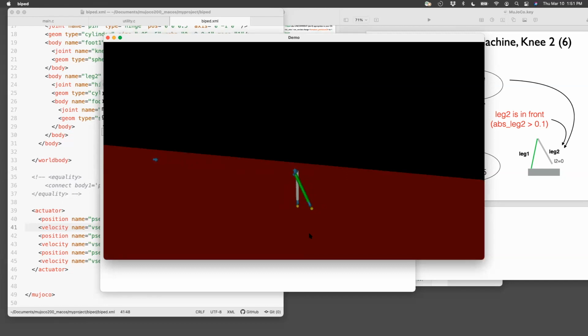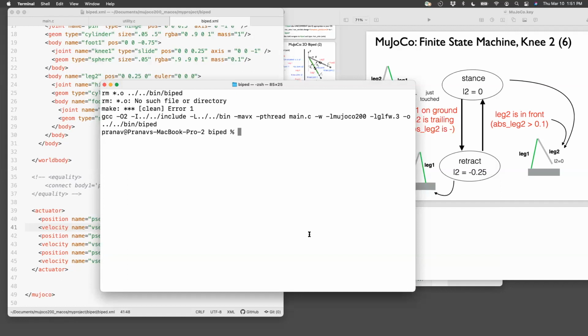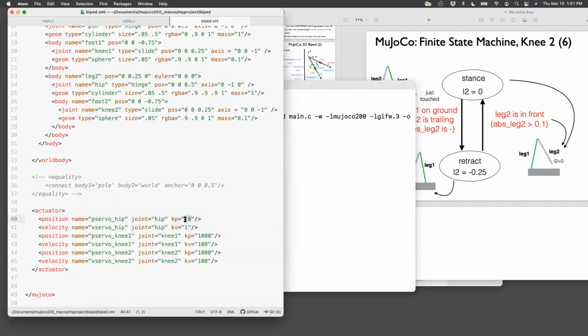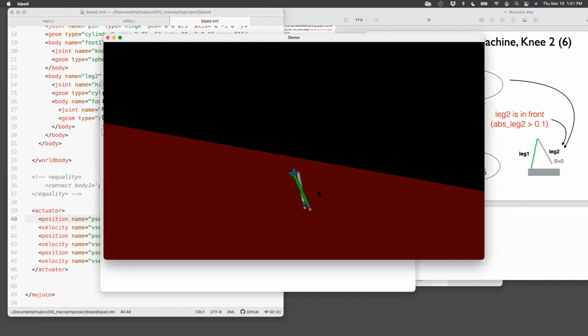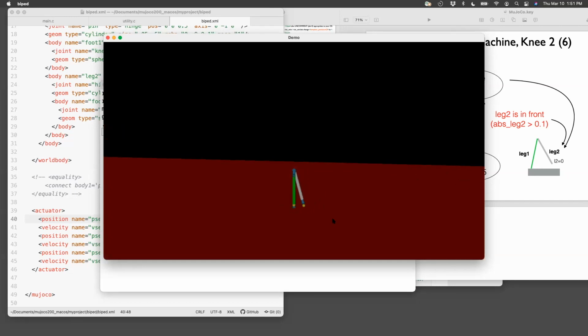You can see that this is what is known as a period 2 gait, or a sort of drunk gait, where it takes a big step with one leg and then takes a short step. If you know a little bit about chaotic solutions and chaos, this basically means that you're very close to the vicinity of a good solution. You just need to tune the numbers so that you get a symmetric gait and not this asymmetric gait. So I'm going to play with this. Let's try 8 and 1. Still is period 2.